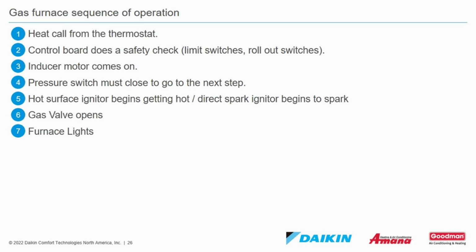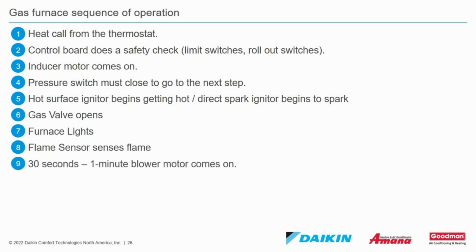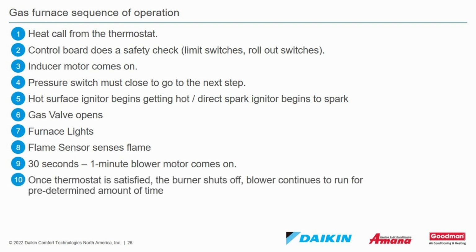7. Furnace lights. 8. Flame sensor senses flame. 9. 30 seconds to 1 minute later, the blower will come on. 10. Once the thermostat is satisfied, the burner shuts off. The blower continues to run for a predetermined amount of time.